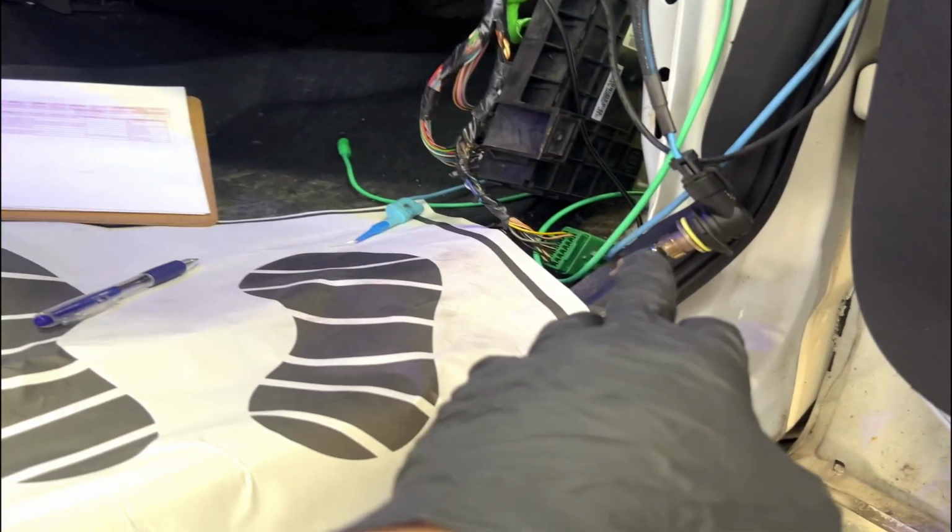We just made all our checks. We got a couple grounds here in this connector, and we checked powers, and the power on this one. The module up in there has all the powers and grounds. We know it has communication because it's obviously talking to the scan tool. There is no ground circuit on the signal return wire or the rotary switch. We have two issues on this truck.